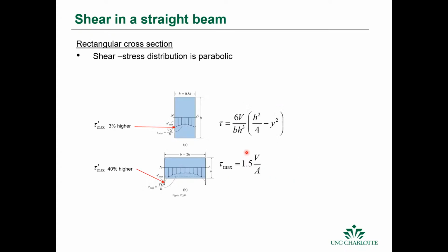And there's some caveats here too, and that is that we can calculate the shear stress for different types of cross-section. If we use the shear formula, which is on the previous slide, we're going to get something like this dashed line. Okay, but in reality, the shear stress is actually parabolic. Okay, so it's not exactly this line or this constant value.